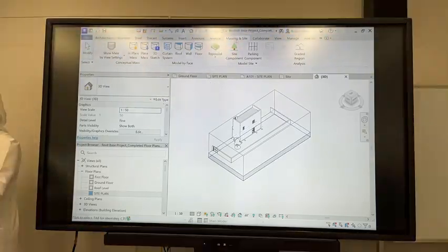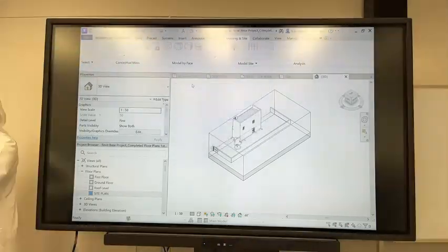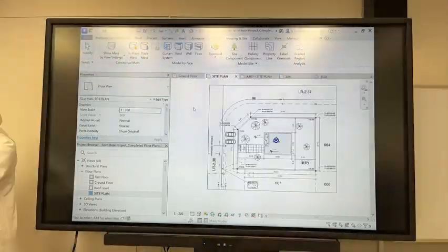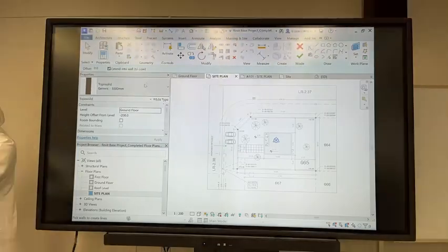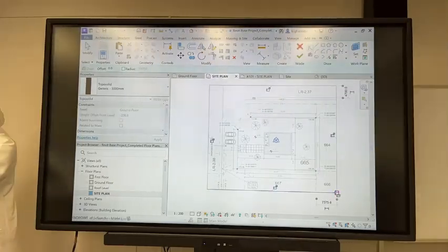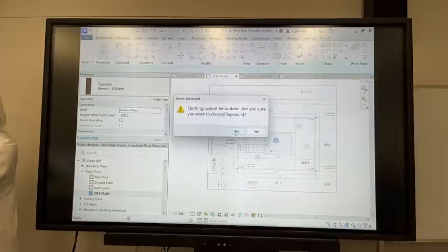Yeah, site, massing and site, topo solid, drop down to create from sketch. Do it on the site plan. So topo solid, create from sketch, generic 3000. Then just like what we do for any floor or slab, you do a rectangle and do it around your whole site. Best, and then you hit the check and it should create it there.